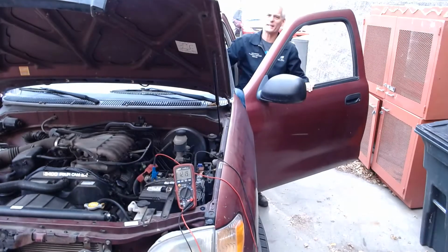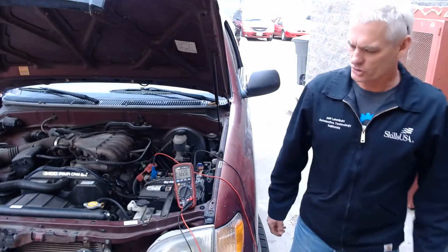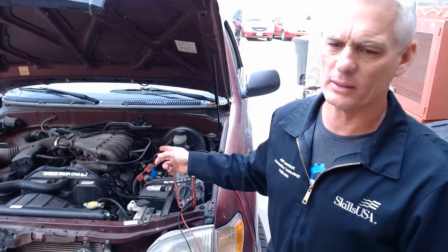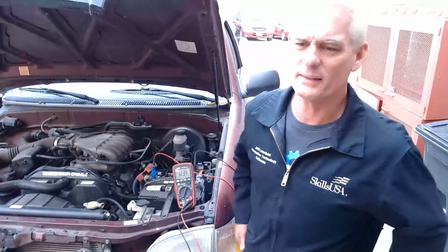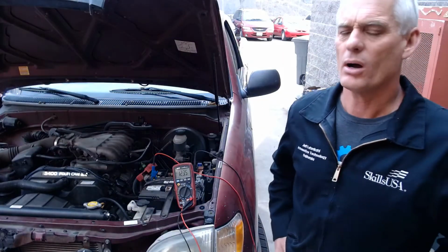So we're starting to get some intermittent contacts on the starter, but if I saw it correctly from inside the car, it looked like it went down to about 11.2 volts while it was cranking. You could hear that a couple of times it cranked and a couple of times it just clicked. So the contacts in the starter are starting to go.